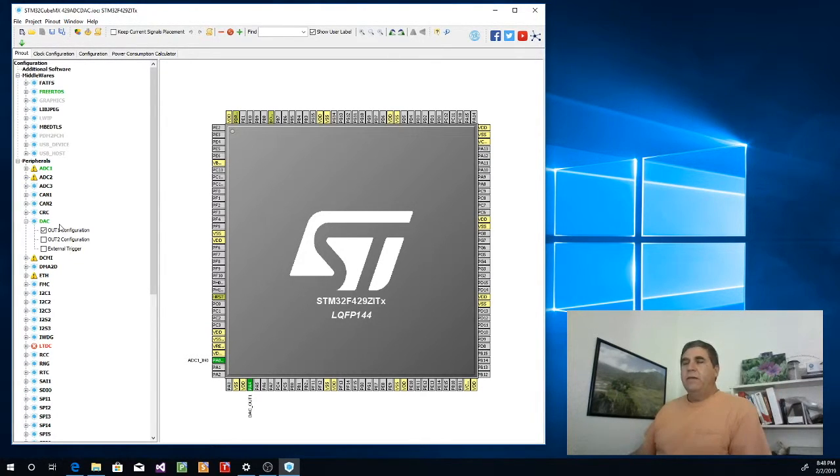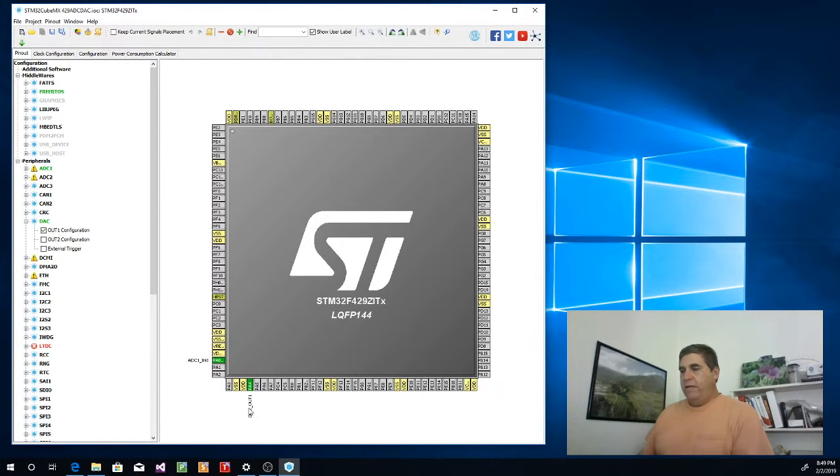Okay, digital to analog conversion is usually done in the processor for 12 bits, and if you need more than that, you are going to have to go to external. And typically, these are not really fast, so their conversion rates are pretty slow. If you need to do high-speed stuff, you won't be doing it on chip. You can see here that I have selected output 1 for the configuration, and output 1 is right here on PA4.